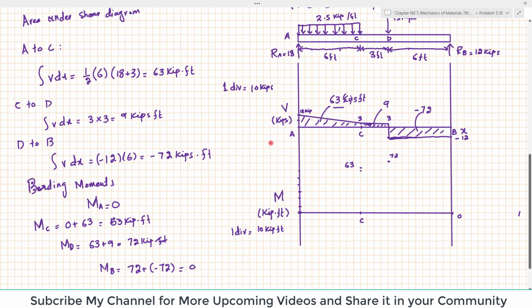Now you can see that this shear force diagram is a linear line and the slope is decreasing. So its bending moment will be a second degree curve, and that will be clockwise. So you can draw it like this from A to C. Now from C to D, you can see the shear force is a constant line with zero slope. So its bending moment will be a first degree line. So it will be a straight line like this.